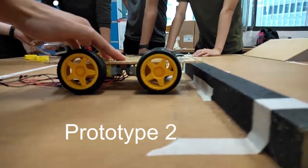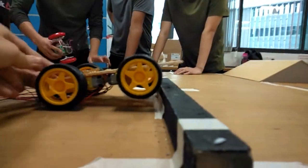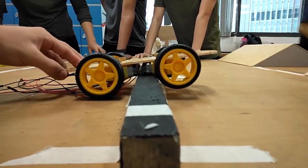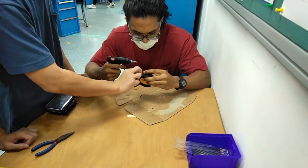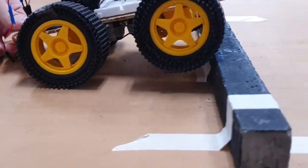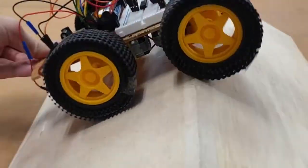In Prototype 2, the motors were getting in the way over the obstacle. This caused our vehicle to suspend in the air and become stationary. To solve this problem, we increased the diameter of the wheels by using layers of anti-slip mat. This could increase the clearance between the motors and the ground.